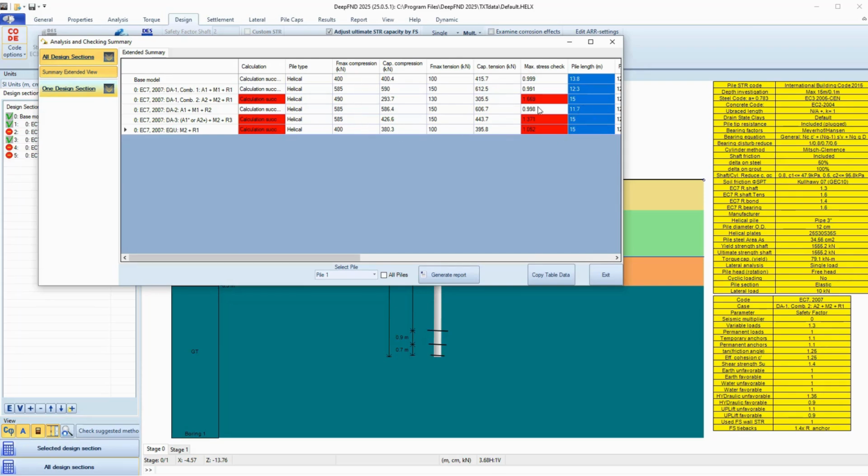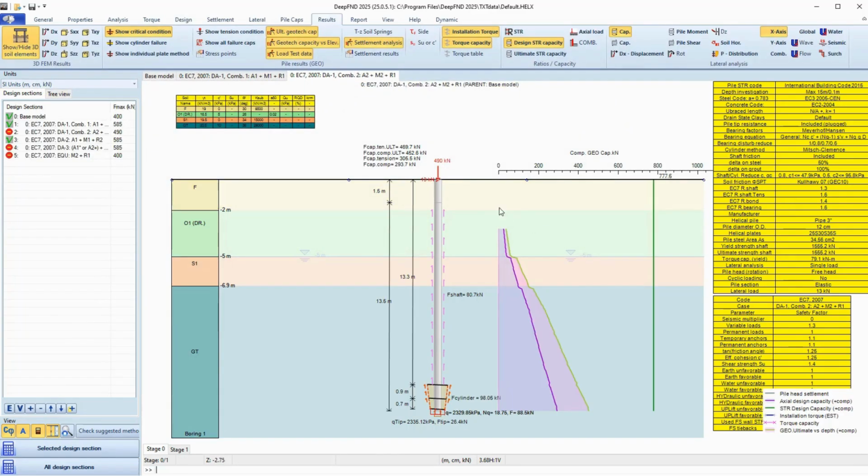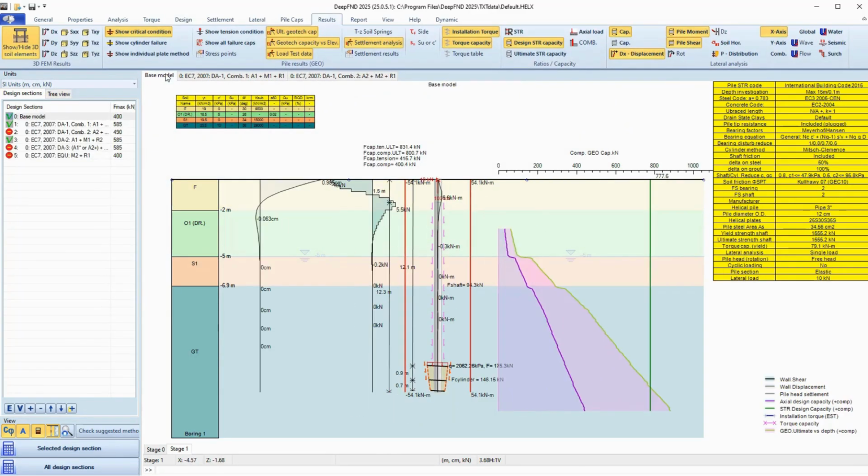We noticed that for some combinations, the maximum specified depth was reached, without the pile being able to develop enough bearing capacity in order to resist the applied factored loads. If we wish to optimize our pile for these exact combinations, then we can consider using bigger or more helical plates, or readjust the maximum optimization depth limit.